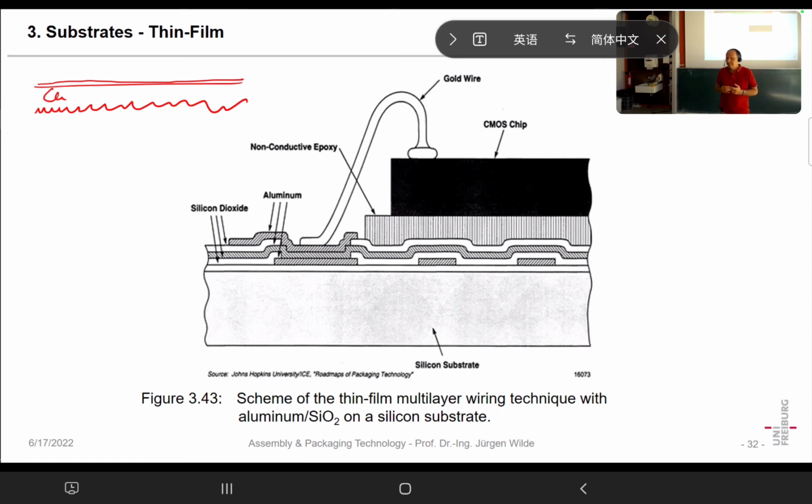And that means their breakdown voltage is also not so high, because maybe in such layers we have 100,000 volts per millimeter, so for 1 micrometer, that means it's breaking down at 100 volts. And that means it's not suited for high voltage applications, of course, but it's fine for high frequency.